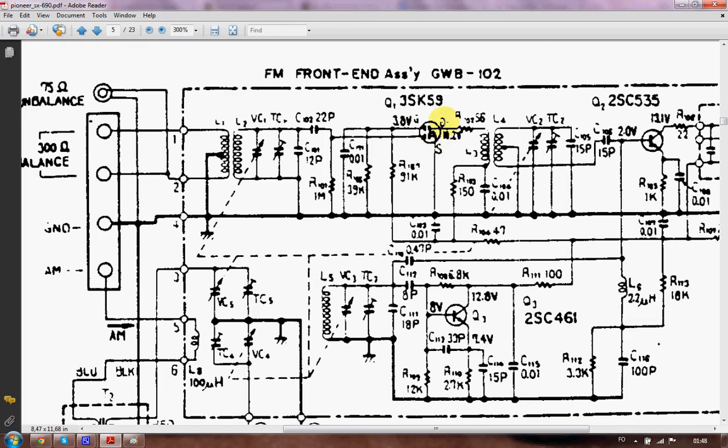Don't look ahead of this. Don't look further through ground. Look further to the source, to the input. Further that way. Further back. And see where, for the first time, you see something that looks like the intended voltage. And then go further forward to see where it disappears, where the fault is.